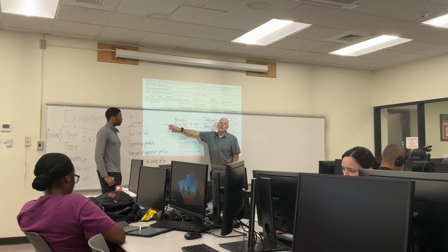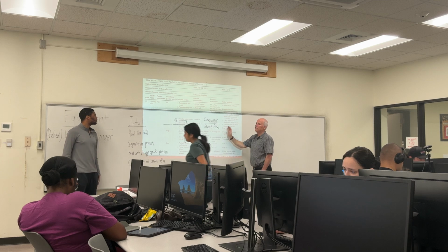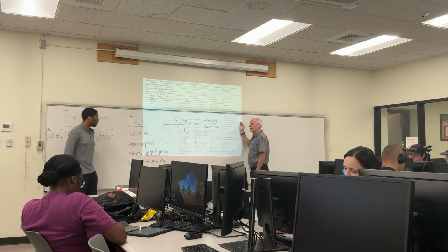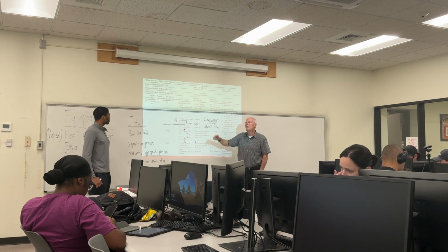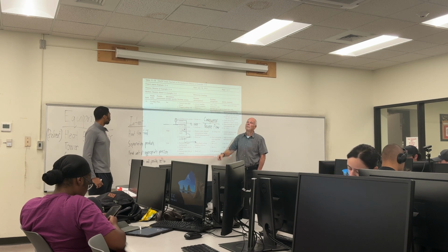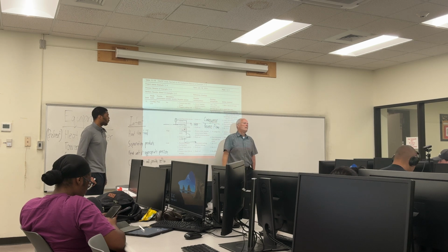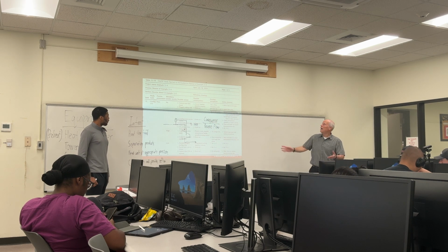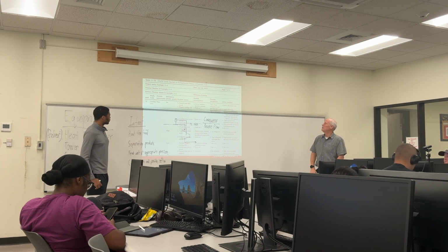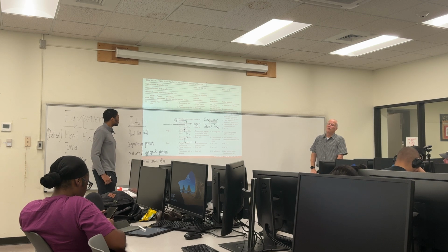And do you think that pressure is going to go away immediately? No. I mean, you have towers, right? You have all kinds of equipment. If that pressure comes back this way, it has plenty of material to send that way to pressure that up. So what could happen on this thing? What's the consequence of reverse flow? Overpressure. Overpressure the pipeline, overpressure the feed equipment.